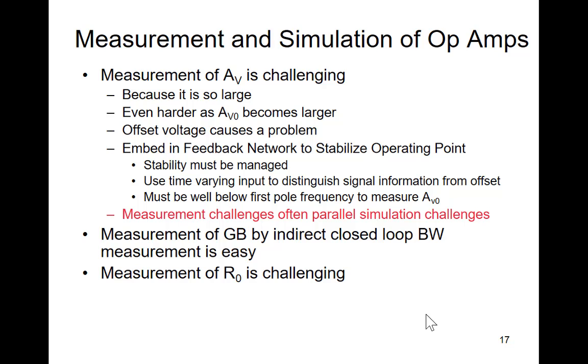Okay, so is there a problem measuring 1 milliohm output impedance? Yeah. Sensitivity. I mean, so much error is going to couple into that. What about putting a 1 milliohm resistor on? Could I put a 1 milliohm resistor on and the voltage drop a factor of 2? Well, it becomes a problem with our measurement instrument at some point. Well, if I had a 1 milliohm resistor, could I make a 1 milliohm resistor? Yeah, that wouldn't be too hard to do. I could get a 1 milliohm resistor if I wanted one very bad.